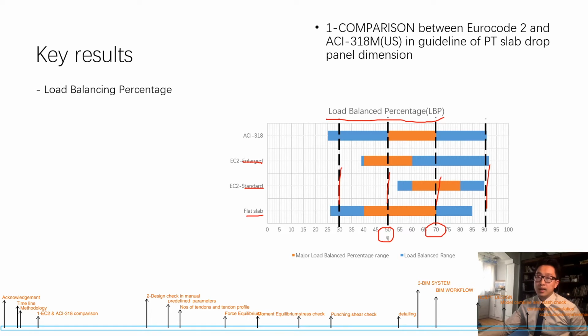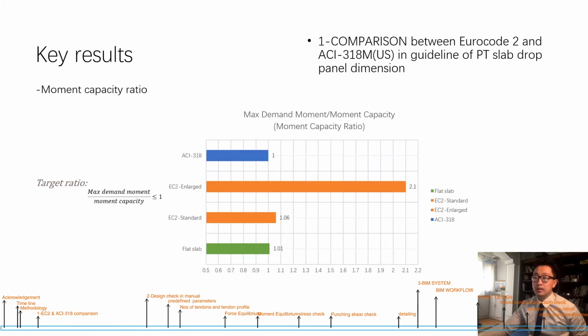So it may turn out higher during construction if the worker is not skilled, and even in the worst case, if the pre-stressing tendon loses its strength, the remaining mild steel is still functional.